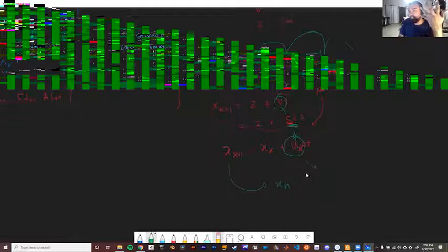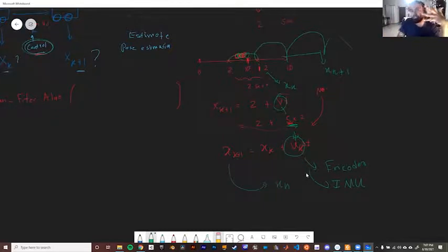Because you're measuring it using something like an encoder, I'm sure all of you know what an encoder is, or something like an IMU, and the measurement itself is uncertain. Plus, as I mentioned before, when the robot is moving, it can slip and some things can go wrong, right? So it's kind of like you're closing your eyes, no observations, you're just counting your steps and navigating. And that's a very dangerous way to operate. And as time goes by, your answer will get worse and worse and worse, and we call that drift, right? So you will drift, okay?